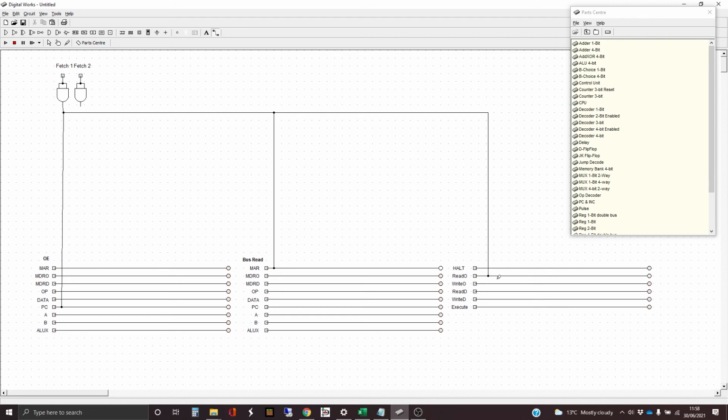I'm just thinking about, no, it's fine. I was just thinking about the fact that that then means if something else connects to read out, it automatically does read D as well. But actually, this isn't true, because if we have more than one thing that wants to connect to one of these outputs, at the moment it would look like we could just drop down lines as far as many as we want. Actually, that's not quite true, because if we have more than one going to the same line, we're going to need to stick an OR gate in, because you can't connect two outputs together.